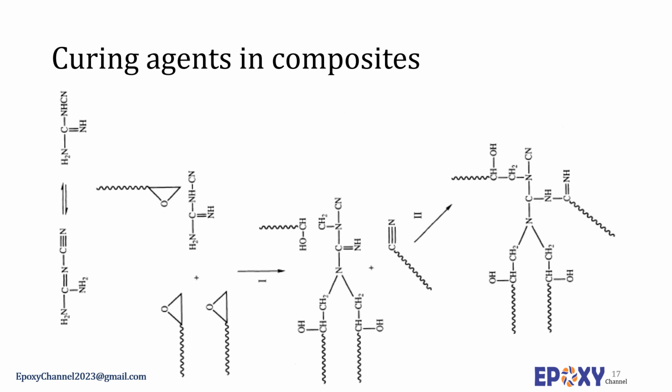It should be pointed out that the complete reaction of the epoxy group is not normally achieved except after long times at high temperatures. This highlights the need for an appropriate post-curing to reach higher heat distortion temperature and chemical resistance.